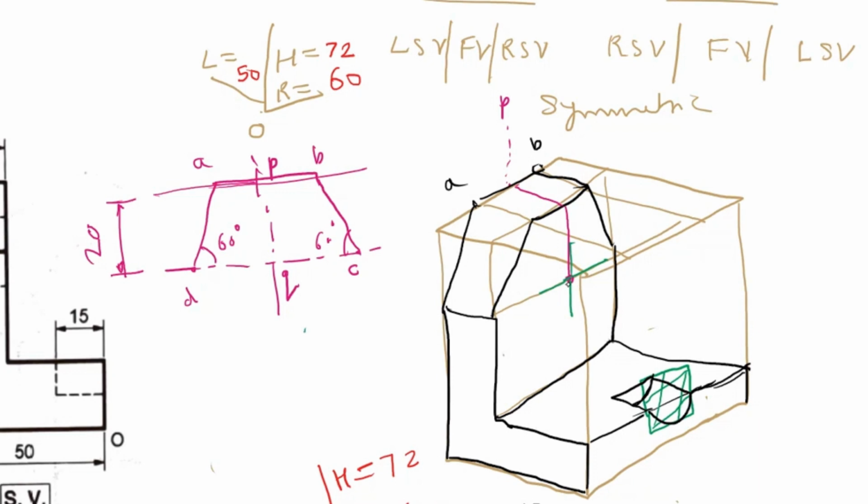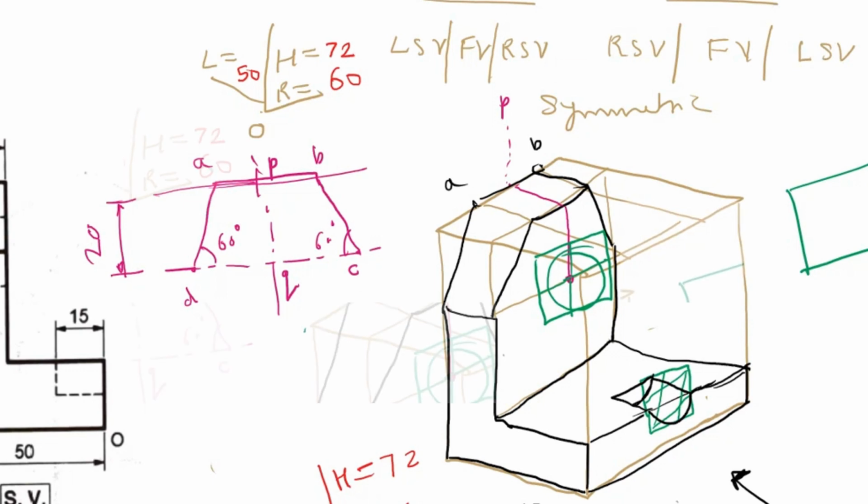You should not draw it like this. You have to draw in which plane? You have to draw in a plane which is parallel to this plane. Okay. So it should be like this only. And once you draw the rhombus, you know how to draw the circle in it, and then how to extend the radius, center points. Hope this is clear to all of you. And then finally you have to draw this which I forward, and right here just draw the arrow. That's it, and your isometric is done.